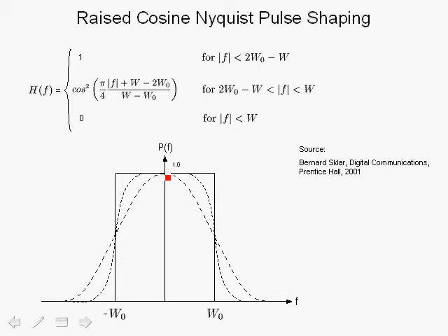But as we mentioned, if you limit the signal and energy in the frequency domain, then it spreads out in the time domain. So by broadening the spectrum in the frequency domain, we actually shrink the time domain, and therefore we may get some better results in terms of both implementation and intersymbol interference.